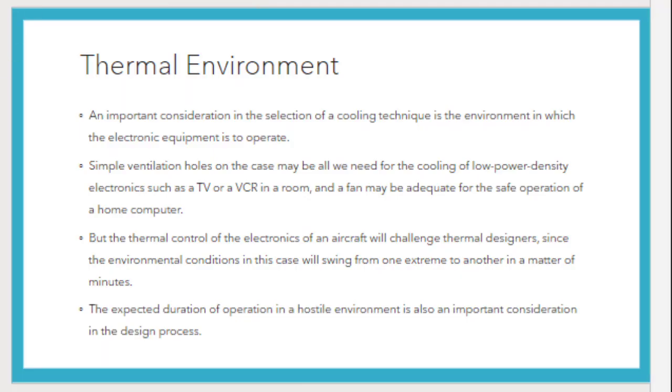Now let us talk about the thermal environment. An important consideration in the selection of a cooling technique is the environment in which the electronic equipment is to operate. Simple ventilation holes on the case may be all we need for the cooling of low power density electronics such as a TV or a VCR in a room, and a fan may be adequate for the safe operation of a home computer.